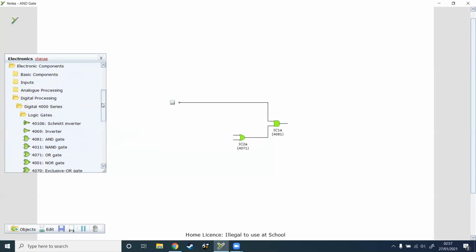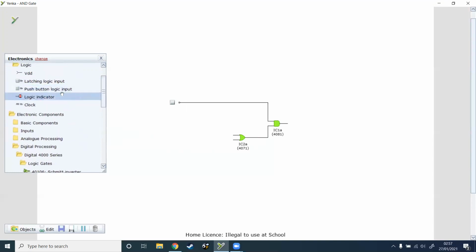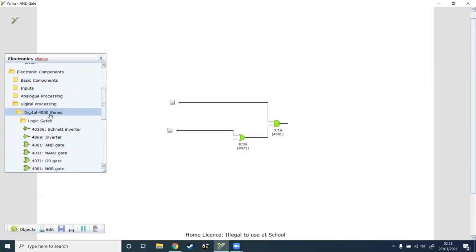And so we've got a switch for the pressure pad. Now I could use the push button here, so it has to be held down, but for demonstration purposes, we'll go with another latching switch. So that's our push pad if that's pressed, and it's if the light beam is broken. So if the light beam is not on, we need an inverter for this, so we'll have our NOT gate in here. We'll connect the NOT gate to the AND gate.